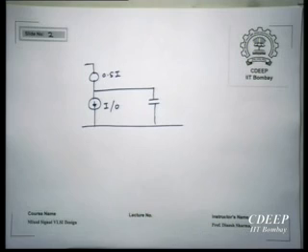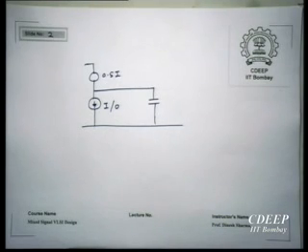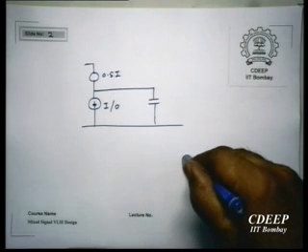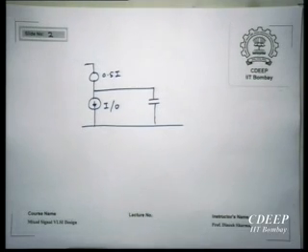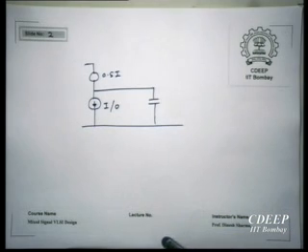However, what happens if because of noise or whatever, mismatch, etc., these two currents are equal? Should these currents become equal, then they will take infinite time to resolve, right? In short, the mismatch between the two currents, which is of the order of delta I by 2, determines the speed of this circuit, right? That means delta I determines the speed of this circuit. So if delta I is large, then my power consumption is large, but on the other hand my speed is good. Okay, so I can now make compromises. Is speed important or power consumption important? And accordingly we can now make this very fast or make it very low power.